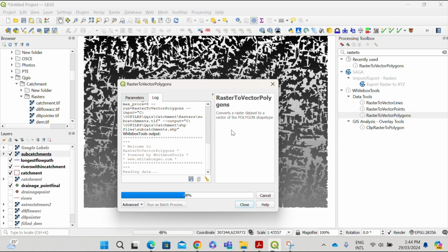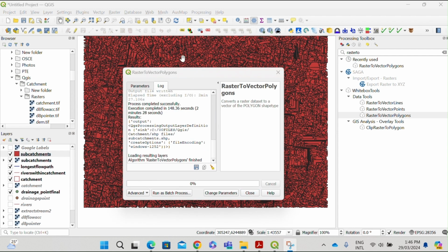Having subbasins will be really helpful during hydrological modeling. It will divide the catchment area into smaller catchments so that we can accurately define the subcatchments and their imperviousness values, the gradient, and every hydrological characteristic so that the result will be similar to the real one. So having subbasins or subcatchments is really beneficial in hydrological modeling. Yeah, there you go. There are so many subbasins.